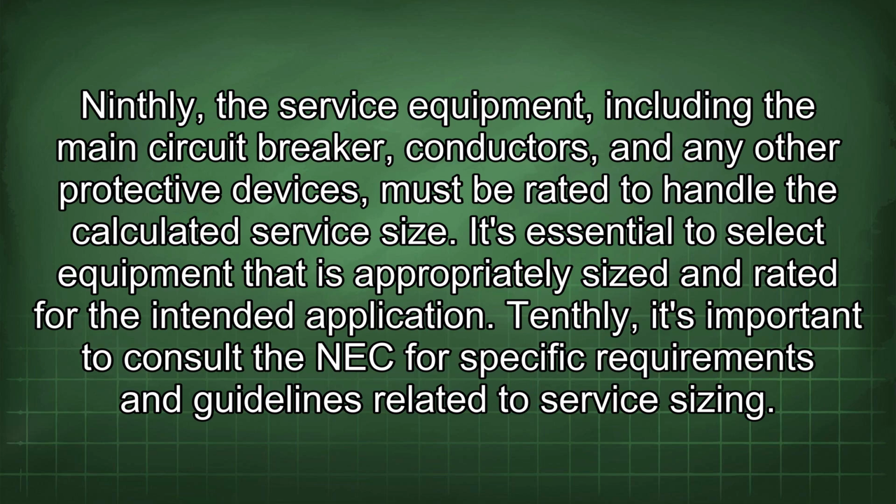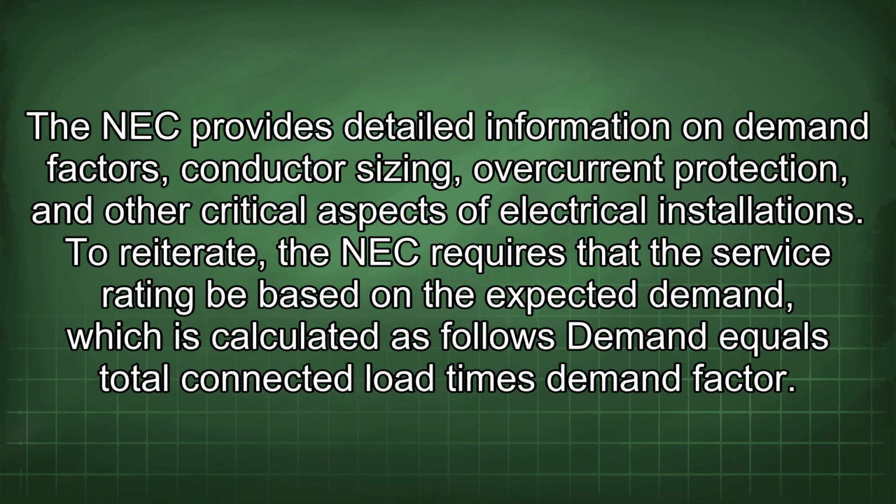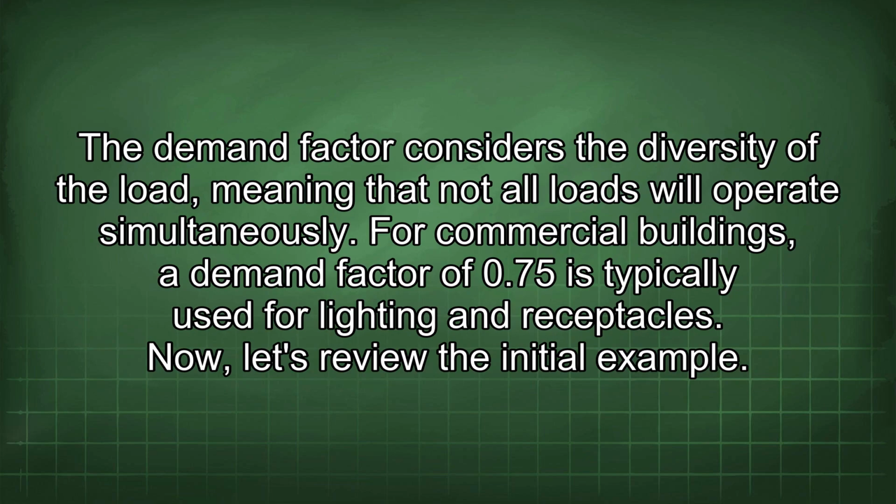Tenthly, it's important to consult the NEC for specific requirements and guidelines related to service sizing. The NEC provides detailed information on demand factors, conductor sizing, overcurrent protection, and other critical aspects of electrical installations. To reiterate, the NEC requires that the service rating be based on the expected demand, which is calculated as follows: demand equals total connected load times demand factor. The demand factor considers the diversity of the load, meaning that not all loads will operate simultaneously. For commercial buildings, a demand factor of 0.75 is typically used for lighting and receptacles.